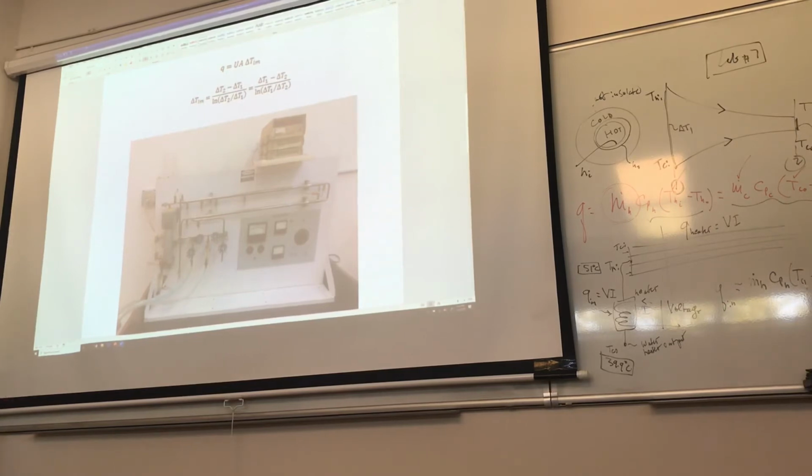So this guy is closed. What happens? The fluid comes in, it's closed through here, so it's not going to do anything. The only path it has to go through is this way, and then up, right? And then come back, and then it enters the jacket right there. As it enters the jacket, now it has to flow in this direction. See? Now it's going opposite what the hot fluid is doing, right? And then it continues on this side.